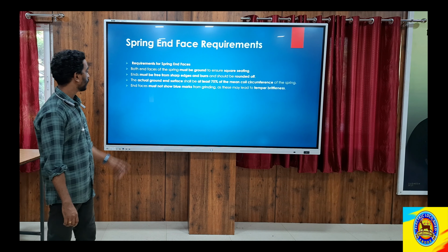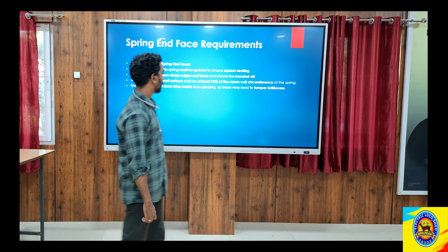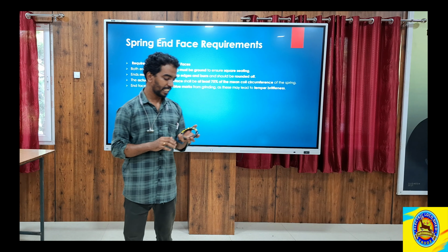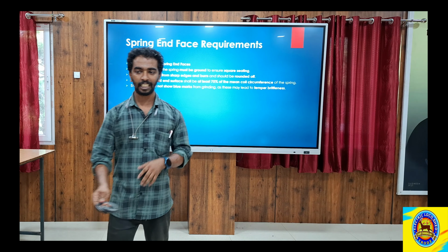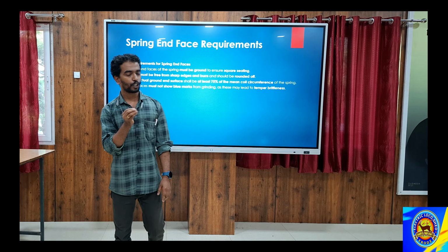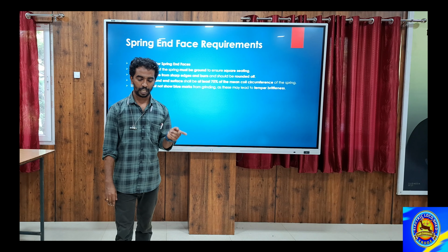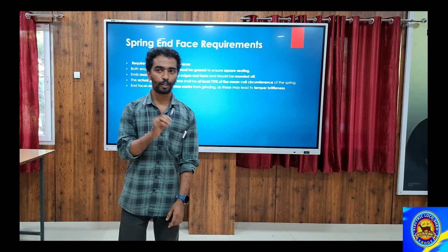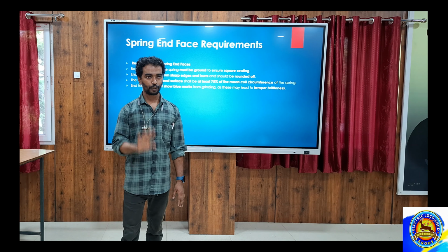The end face must not show blow marks from grinding, as these may lead to temper brittleness. Grinding is the process used to get this finishing. While doing grinding, maybe they will apply extra pressure, or otherwise they will not use proper liquid for cooling it. That may lead to hotspots in the material. That hotspot damages the material strength and further leads to cracks.